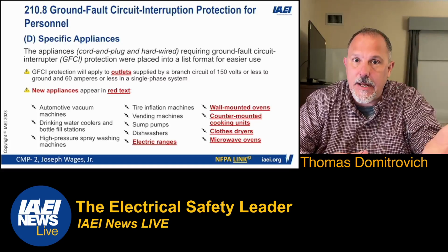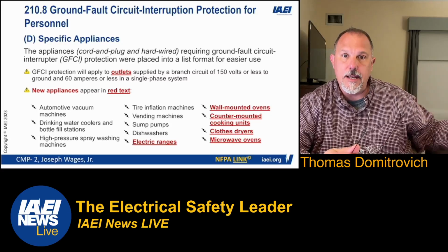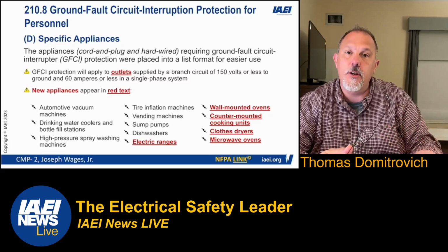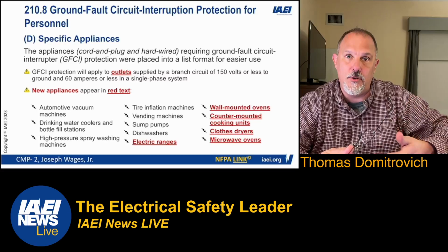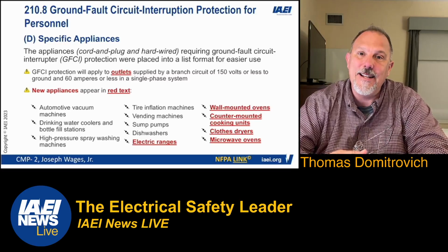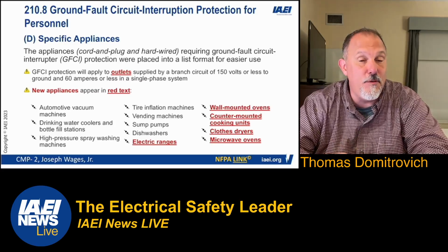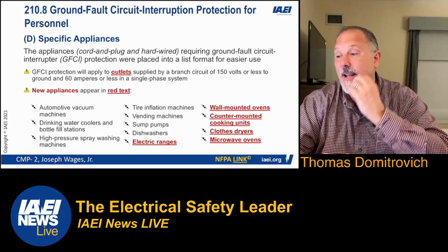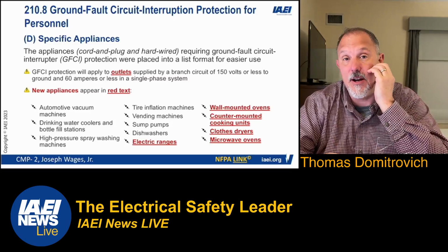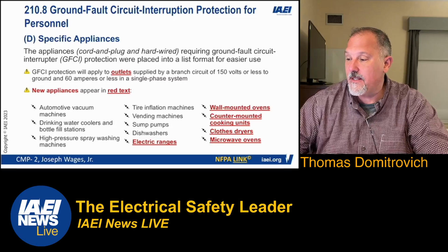In some appliances, like some dishwashers, they'll ship with a cord that you plug in, or they'll just ship it with the termination, so you wire directly to the dishwasher. And now it's no longer cord and plug connected. Now you're not required to have GFCI protection as per 210.8(A). And the question is, did they remove the hazard simply because they hardwired it? And the answer to that is no, they did not remove the hazard. The hazard is still there. So we had this discussion.